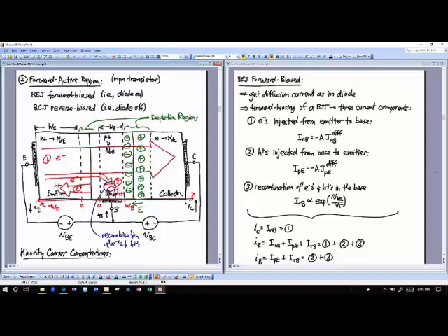Okay? Now these currents that you're looking at, they are not drift currents. They are diffusion currents. Right? They're happening just like it happens in a diode because I have a very large difference in concentration between carriers at one location and carriers on the other location. So it is diffusion current. Right? Do you think I'm going to ask something about that on the exam? Yeah, I probably will. I want to make sure you understand the concept of diffusion versus drift.